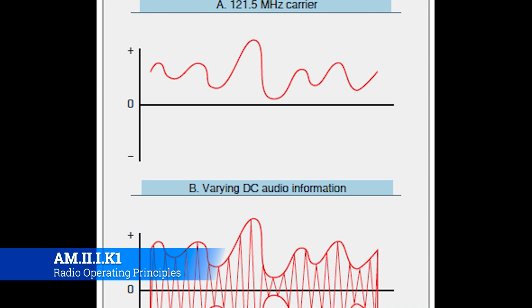You need to be able to modulate it, through either amplitude modulation or frequency modulation, to create the data that you want to transmit. Alright, so what happens is, if you look at graphic A, there's a carrier wave, a standard radio wave, and then you also create another wave that basically holds that data.